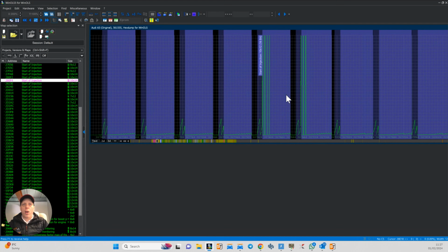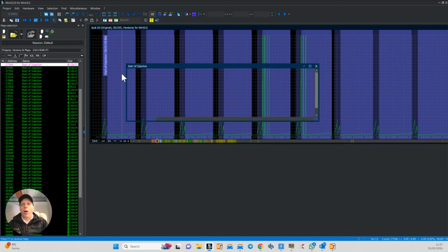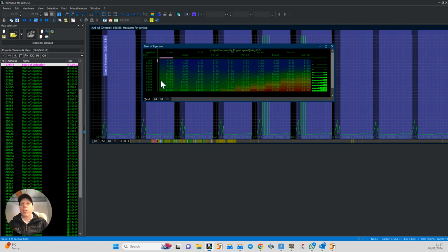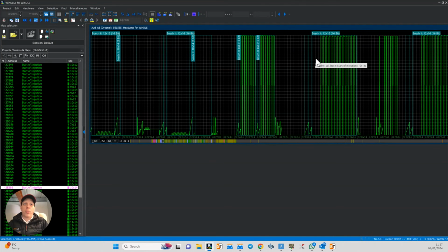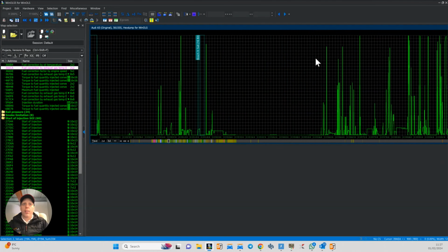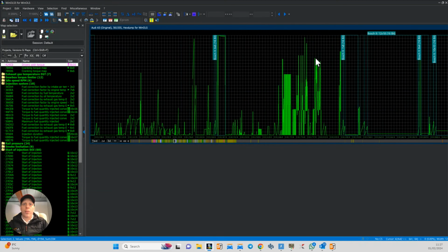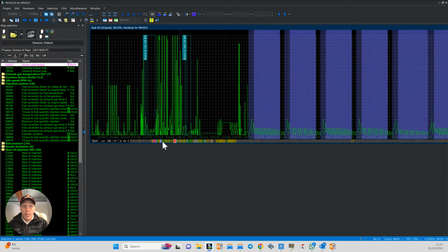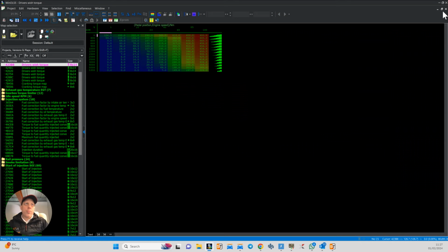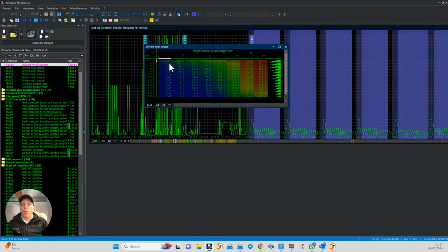So it's not only telling you what they are, it's now also putting all the information inside of the map itself. So if we go to that driver's wish table, as was earlier, go to one that you've already seen, it's now put it into like a view, so you can now see what's going on. So you've got like 1% throttle, 100% throttle, so it's telling you what it is, pedal position. You've got RPM, so now that makes sense.